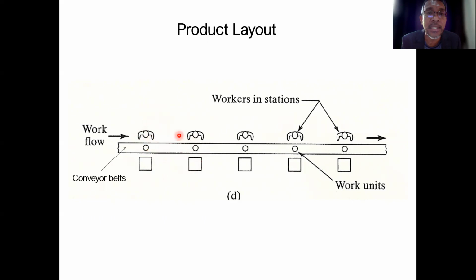To balance up the process, line balancing makes the work equal for each operator. They will divide it based on the cycle time for one operator. So this one is 30 seconds, this one also around 30 seconds, 30 seconds, 30 seconds. So we can produce the product with the correct sequence and flow.